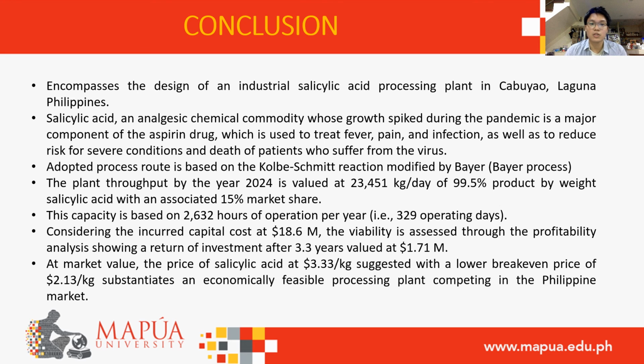The production of salicylic acid will also utilize the Kolbe-Schmitt reaction, which was modified by the Bayer process. This includes the two-step carboxylation process at which two temperature shifts are required to yield a conversion of 90%. Moreover, a detailed planning and computation had led to the completion of the study. This includes the fundamental background, market appraisal, hazard study, economic analysis, and etc.